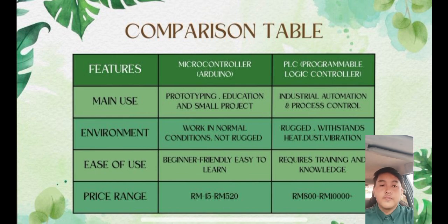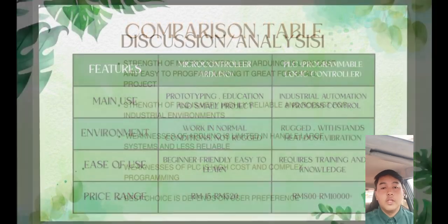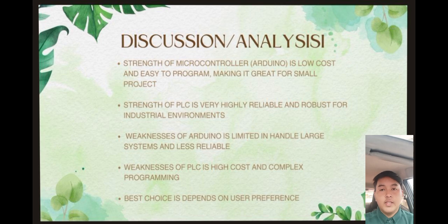Now, let's move to discussion and analysis. The strengths of Arduino are its low cost and ease of programming, and it is suitable for small projects, while PLCs are very reliable and strong in industrial environments. But both have a drawback. Arduino is less reliable for big systems, while PLCs are costly and more complex to program.